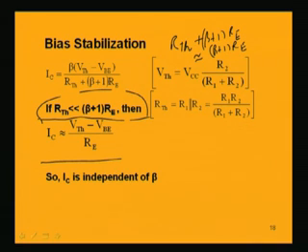And here one thing is to be noted: since we are having two resistances R1 and R2, we can very well find a combination of R1 and R2, the values being small of course, and their parallel combination will be still smaller. So, that can be made small in comparison with (beta plus 1) RE, and it is more flexible in the sense that when we had only RB, one resistance, in earlier cases, to make RB very small was difficult, because other criteria will also be there.